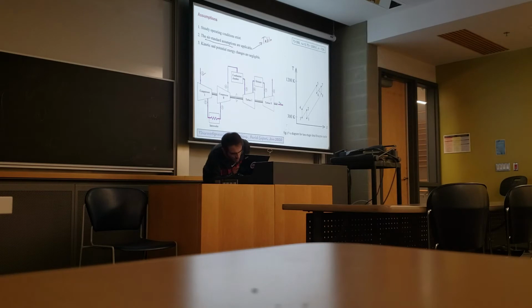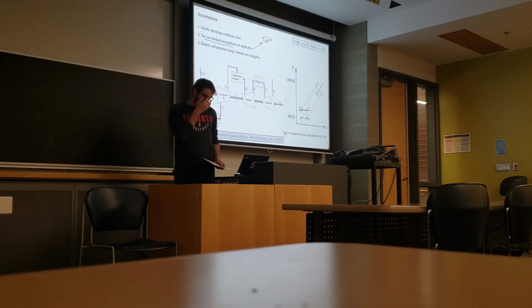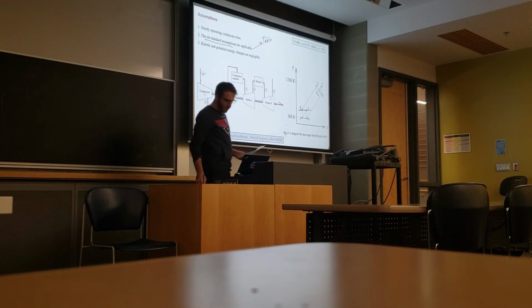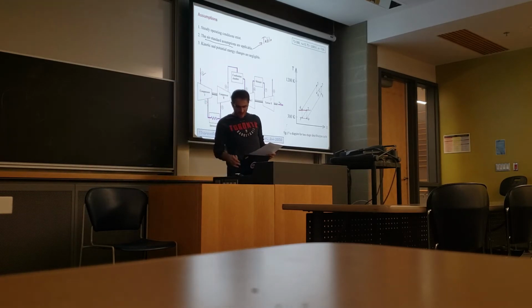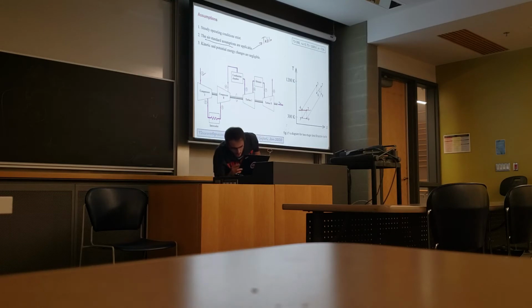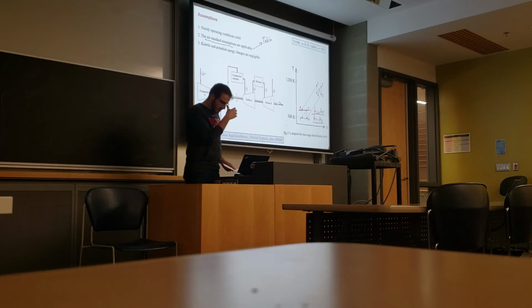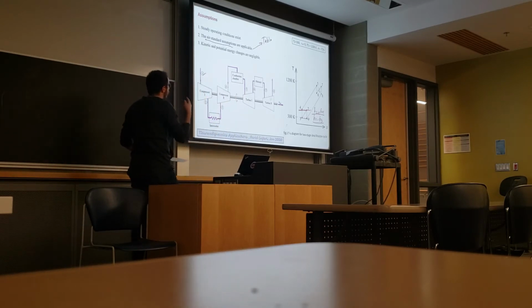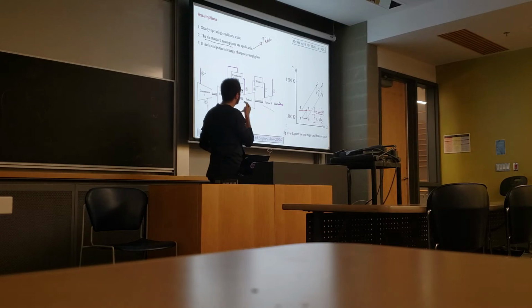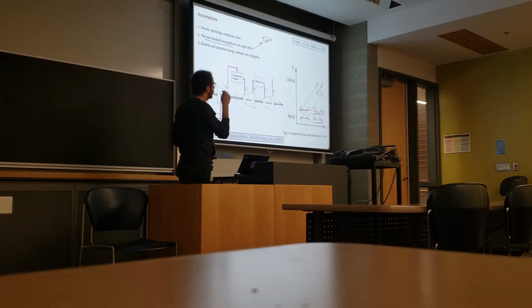So you see here, 1 and 3 are on the same constant temperature line, and 2 and 4 are on the other constant temperature line. Basically it means that H2 equals H4 in this case, and H1 equals H3. This is the case just for the ideal Brayton cycle, where the compression ratios are equal.